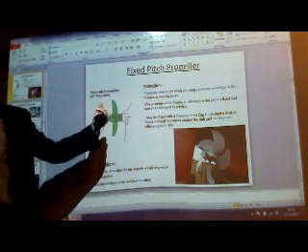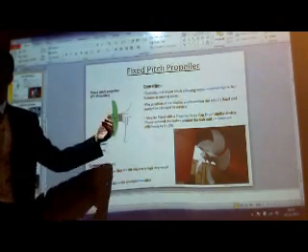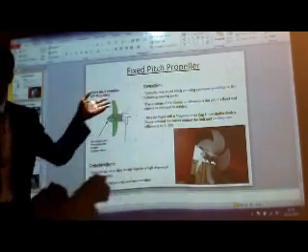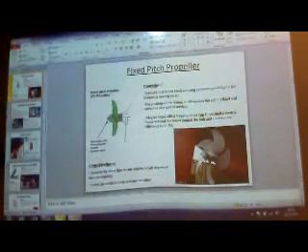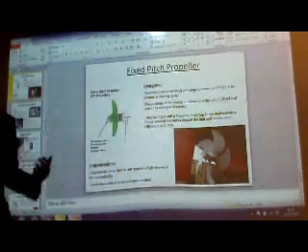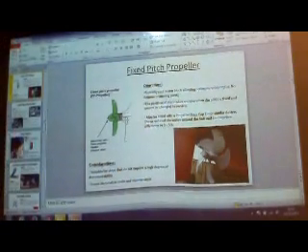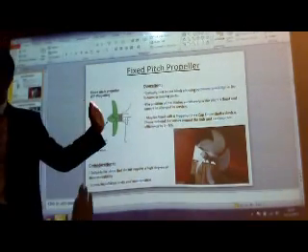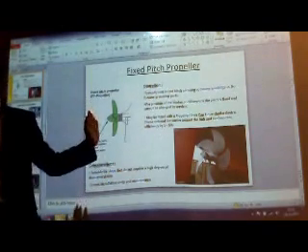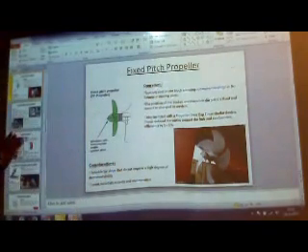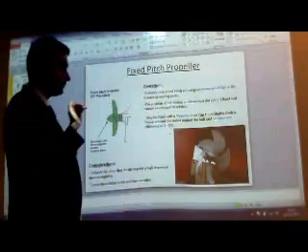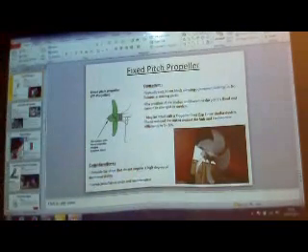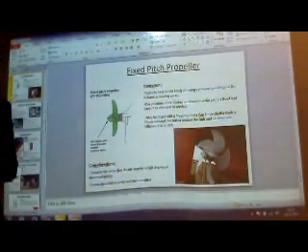You can change the pitch, or you can change the revolutions, which will then directly relate to your vessel's linear speed, or the propulsion that you are generating. So in this case, the pitch is fixed. So what are you left with? RPM. So if you change the RPM up and down, what is going to happen? That would then decide how fast or slow this ship is going to be propelled.